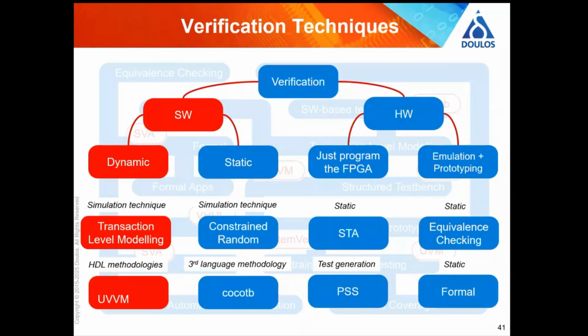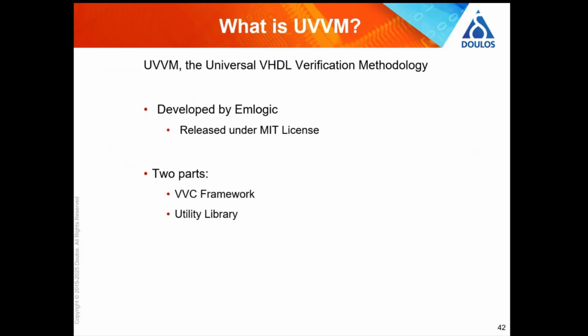So the next methodology I'm going to talk about is the rival, if you like, to OSVVM, which is UVVM, Universal VHDL Verification Methodology. It's not the same, but it's the same idea. It consists of test bench Lego, again, a standard way of creating and joining together pieces of your test bench, and a whole bunch of useful packages with lots of useful things in to make it easier for you to write a test bench.